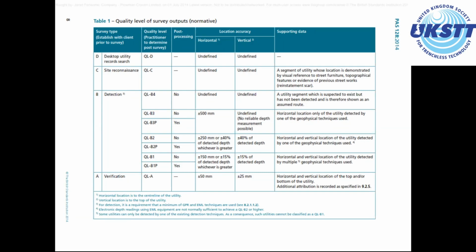So it can be interrogated within an office environment by a trained user or geophysicist. The data can be manipulated further to highlight certain aspects, removal of noise from features encountered on site, and in turn gives the capability to look for further subsurface features such as voids, ground movement, cracking, or obstructions in regards to concrete slabs or reinforcement.